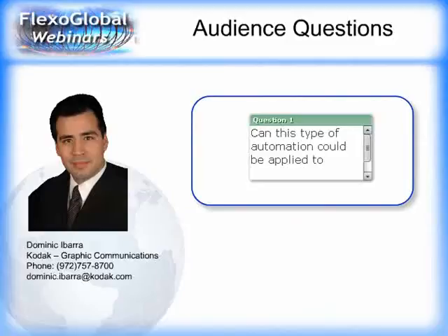Yes, it can. In fact, flexography is probably the area I deal with the most. What we find is the automation is invaluable in that it reduces the amount of decisions an operator has to make on output. We're not here to speed up the very complicated one-up preparation steps. We're really focusing on the output and decision-making processes. So when you're choosing reverse print, surface print, line strains, plates, distortion, all those many different variables and complicated choices, those can all be automated into a single system, so that every output has only one possible output condition.